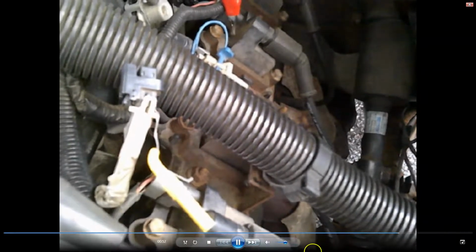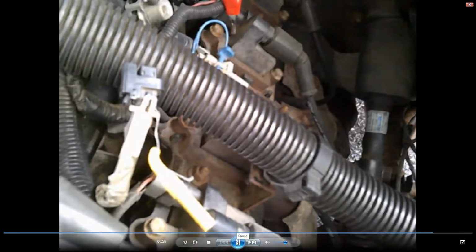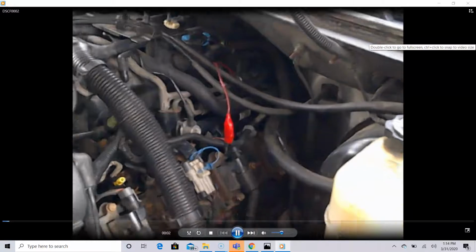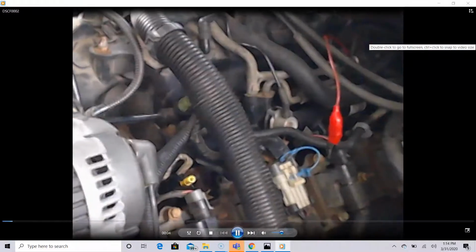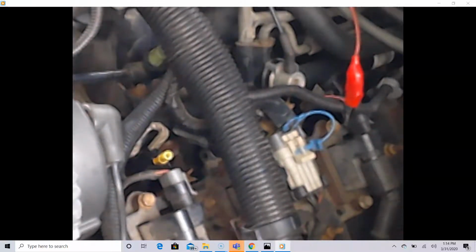I'm going to get that plug back in, and as soon as I get that plugged in, I will resume, and we'll do the voltage drop on the injector. All right, so you can see the yellow connector that's back probed into the positive wire going to the fuel injector. That's into the pink wire. Again, in the lab, you're J-kitting between the injector and the connector for the injector, and then you can attach your stuff to it. You do not back probe in the lab. Okay, so that is hooked up.